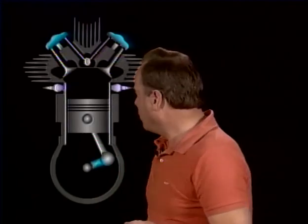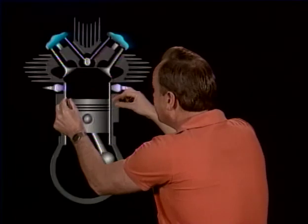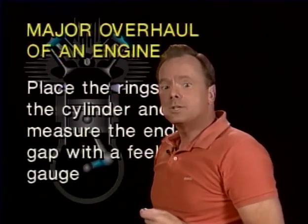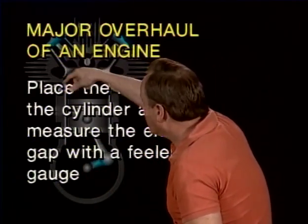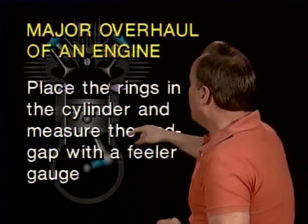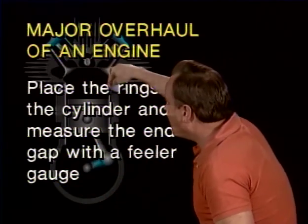All right, during the major overhaul of an engine, they say you should check proper end gap clearance on piston rings. The way you should do that is you want to make sure that piston rings fit inside the cylinder and leave the proper gap at the end of the piston rings. How do you do that? The answer is you take the piston ring off of the piston and put it in the cylinder by itself, and then measure the end gap with a feeler gauge. You put the ring in the cylinder without the piston being there and measure the gap with a feeler gauge.